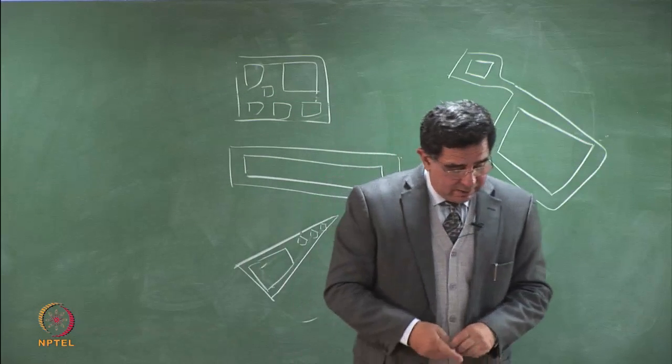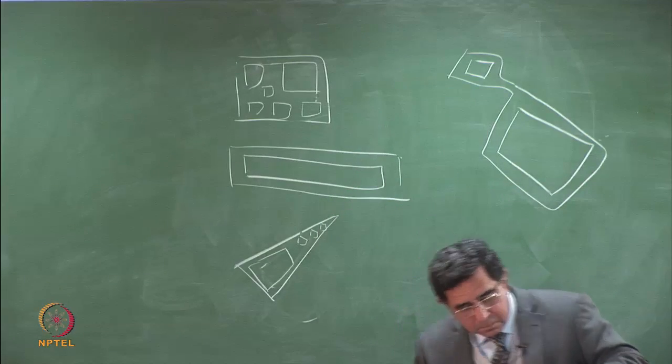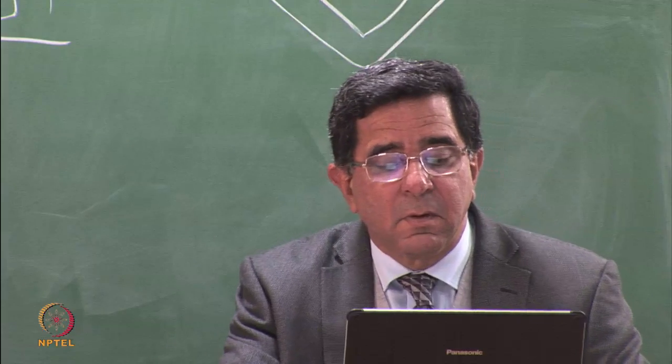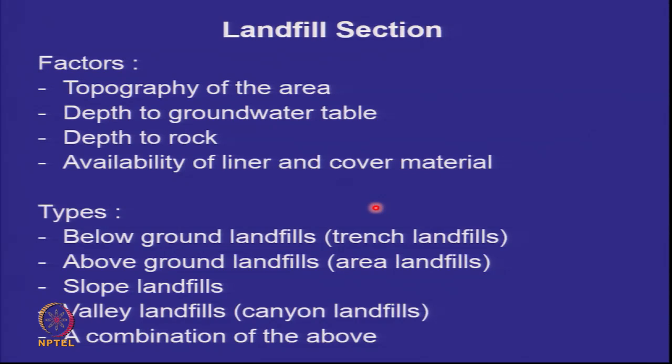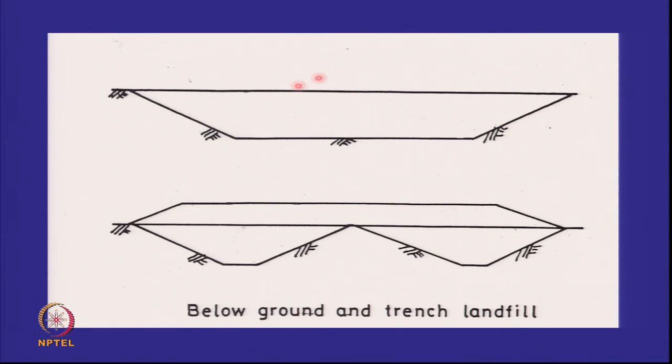What does the section look like? The landfill section will be dependent on the topography of the area. And as I said, it will depend on the depth to groundwater table and depth to rock. And you can have below ground landfills, above ground landfills, sloping landfills, valley landfills, and combinations of the above. So I'll run through this quickly. That's a below ground landfill,